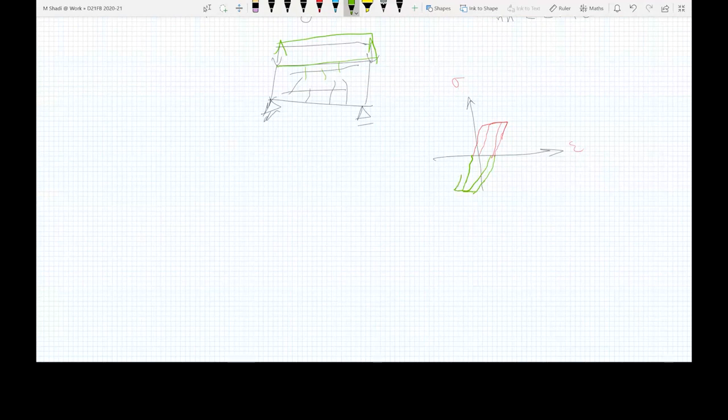You push it back slightly further, and then you come back, and then you keep moving through this cycle several times, probably come back at this point, and then start over, push it, and then probably you fail at this point. Probably it is not complete failure. There is still some strength in this material. And you keep repeating this cycle several times. And by the way, this type of cycles would happen if you have an earthquake. If you have an earthquake, this cyclic loading would happen.